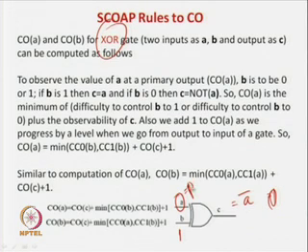So, that is why we call the XOR gate a controlled inverter, because if one input is 1, then the other input actually gets inverted. Similarly, if you apply a 0 over here, then C will be equal to A. So, that is the idea. Either you get A or you get A prime, depending on whether you apply a 0 or a 1.